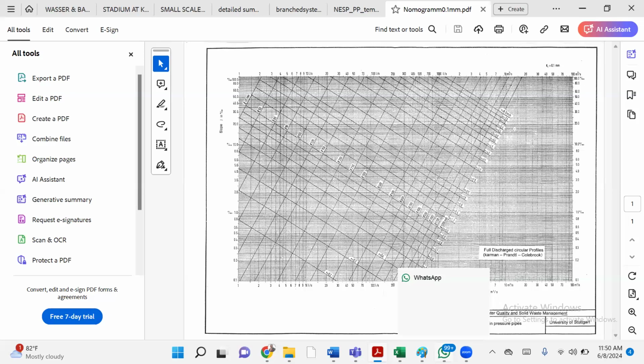But now this is where your wisdom as an engineer comes in. If it's too close to 100, to save money for the client, you use 100 because you already factored in a factor of safety. And if 125 is not in the market, I don't think we have 125 in the market. All we have is 100 and 150. So you use 100. It will flow, because I've already doubled.